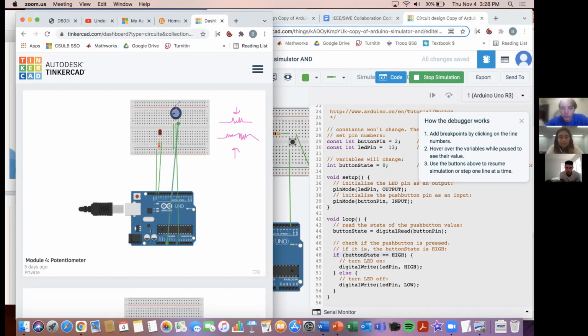This potentiometer, I'm going to draw out with the resistor. So your resistance inside looks something like this, and it's going to determine how much it wants to cut off here. And so that's how you determine how much resistance you want to provide to the circuit for the potentiometer. And so let me now show you guys how you want to set it up.